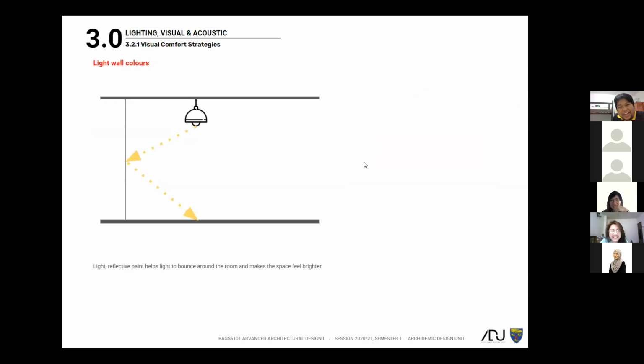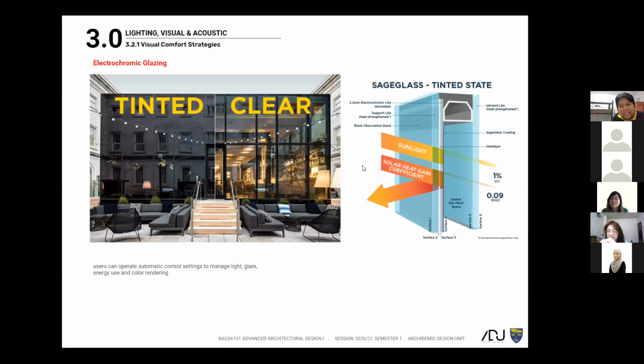Next. You can also use other things, like a Malaysian product called Crystal Bond, with a K. Crystal Bond has been in the market for a long time, and they've been using it a lot on cars, but they also do it on buildings. I've used it myself on some buildings. It might not give you any tint. It allows almost 99% of the light to come in, but it blocks 99% of UV, so you don't get the heat. You get light, no heat.